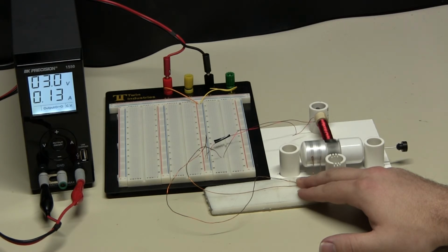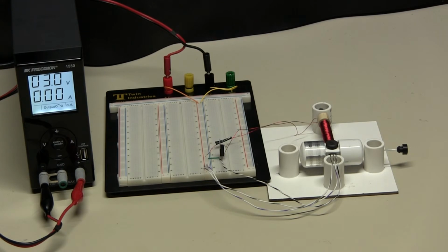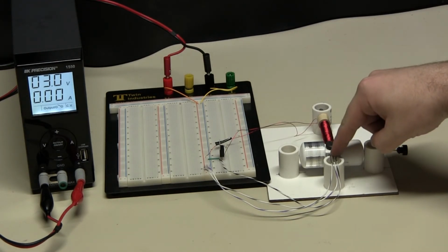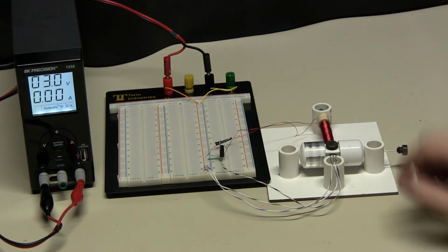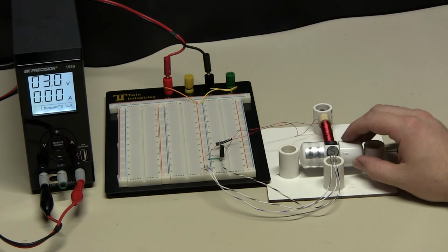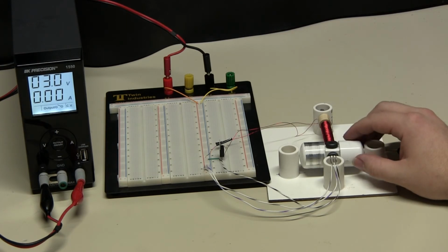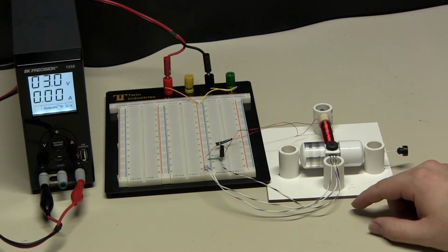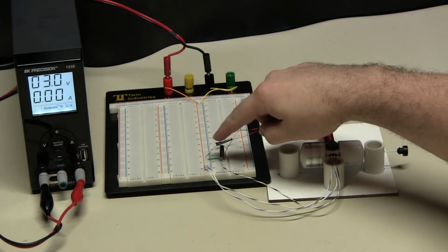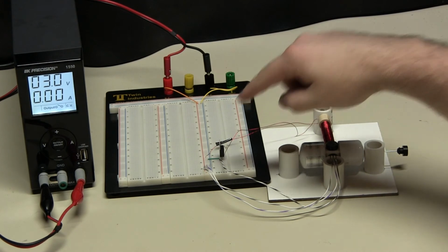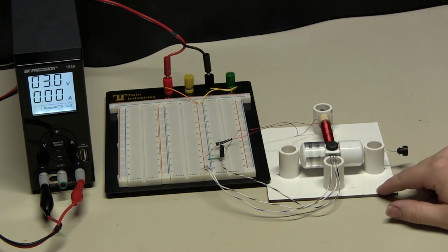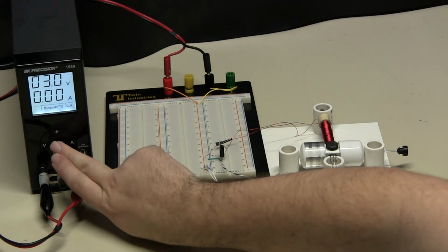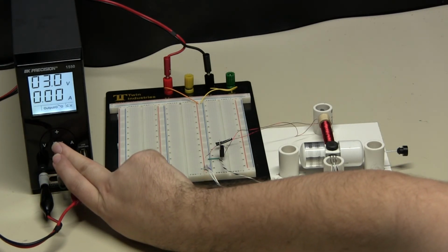traditional brushed DC motors. I've now replaced the brush type commutator with a Hall effect sensor. It's on the back side of this post. The Hall effect sensor in this case responds to the south pole of a magnet, closing the circuit just like the aluminum strips did before with the commutator. That weak Hall effect signal is sent to this power transistor, which acts as a solid state switch to turn the motor on. Now I've made no changes to the power supply for voltage, but notice how much faster and quieter the motor runs.